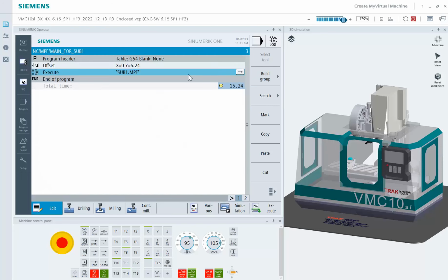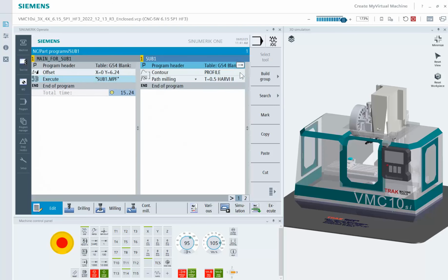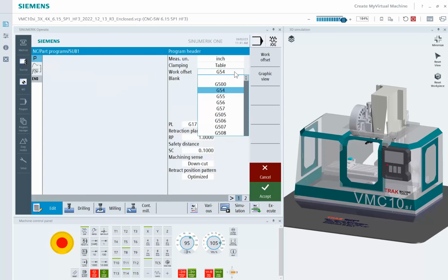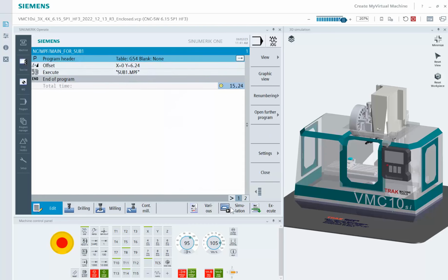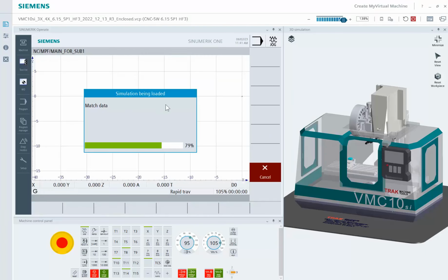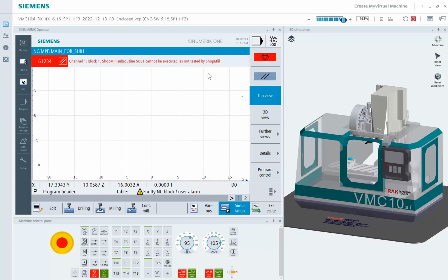Now what's cool with the sub, if I expand over on this event, I can actually open up the sub program. So now I can come in and get rid of the work coordinate. For my purposes right now, this can get closed. What I'm looking to see is that feature shifted up in space relative to wherever my coordinate 0 is.